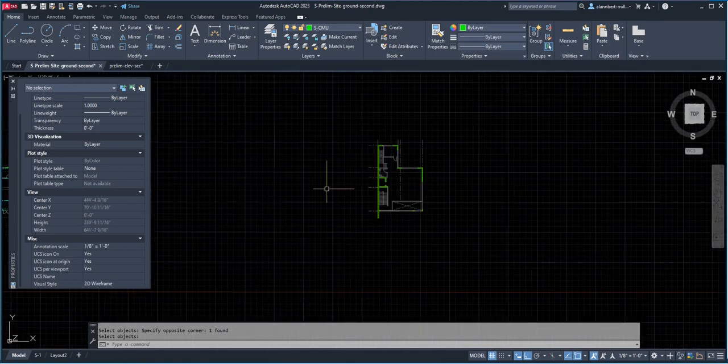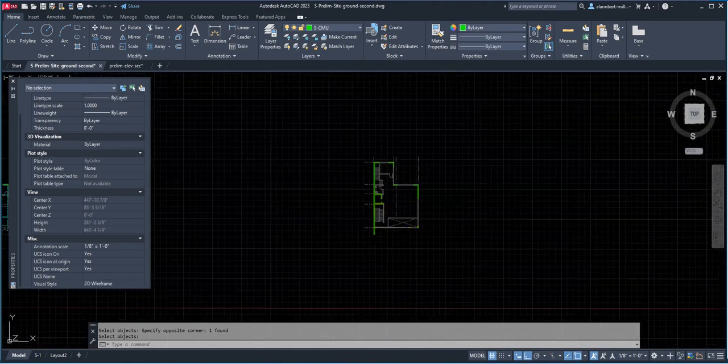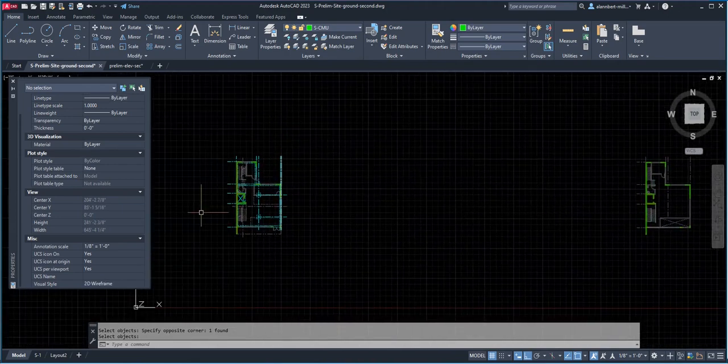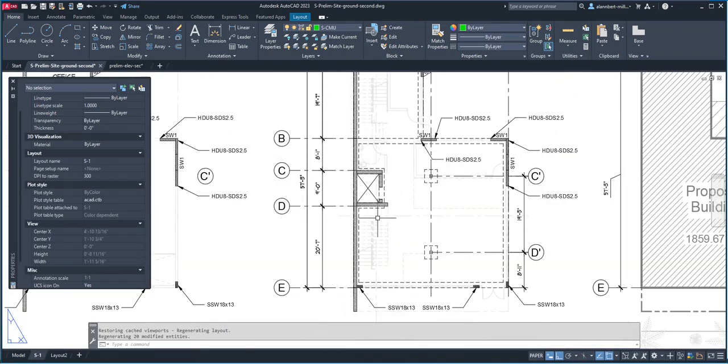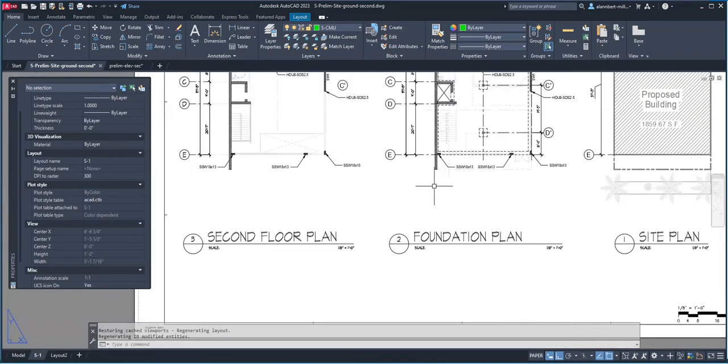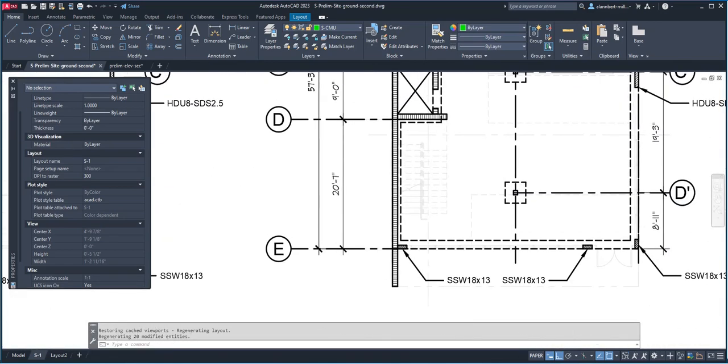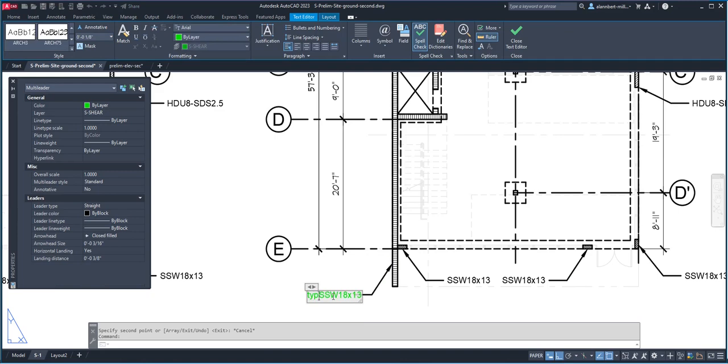Okay, all right. So again, CMU walls. That's how it's done. And then let's go ahead now to layout and make sure that anybody who is working on this construction on this building knows that this is a CMU wall. So we're going to simply do a copy of this one, and we're going to copy from here to here. And we're going to label and change this to typical. Remember that we always use all capitals. So typical 6-inch CMU wall.